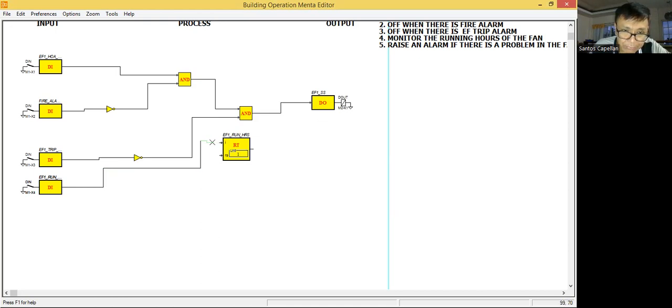But if you don't have the luxury of time, especially if you are pressured in the site, then your project manager will say finish the programming within several days. Then maybe you will not be very careful in your function block programming, especially these lines, these nodes. Now I already have provided the input. Then I will provide here the RS. Now RS is for the reset.